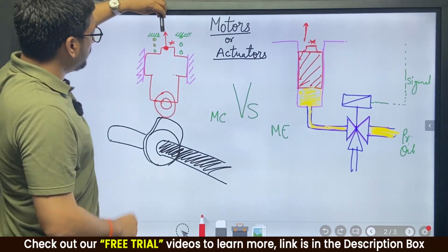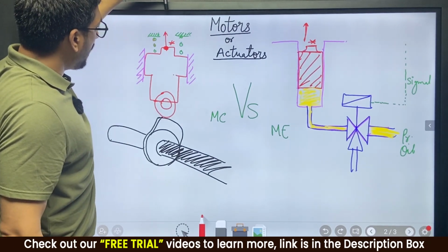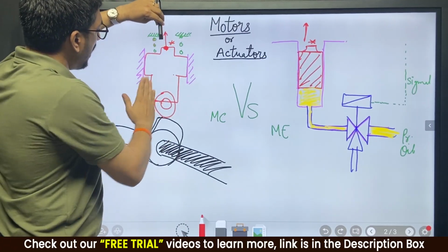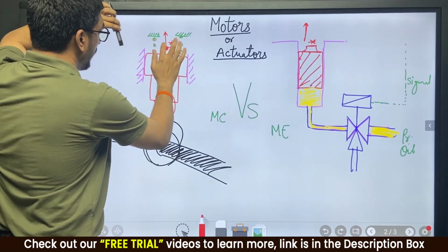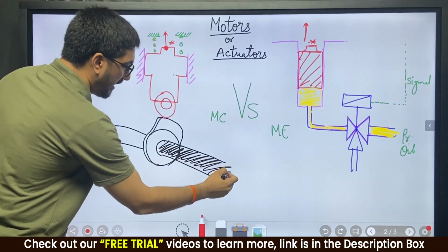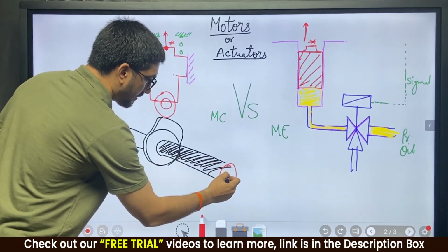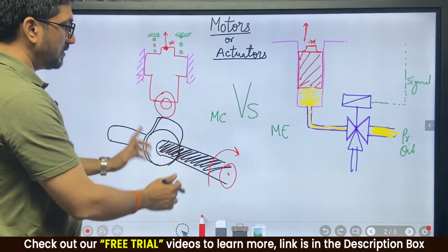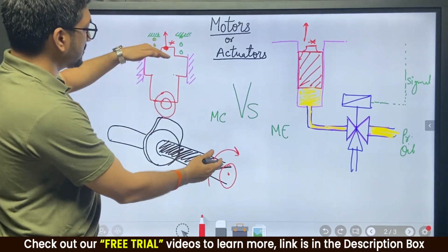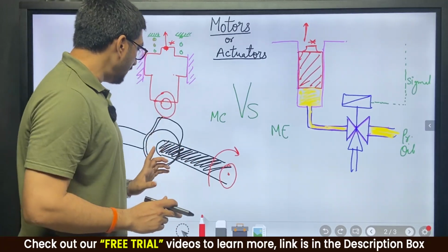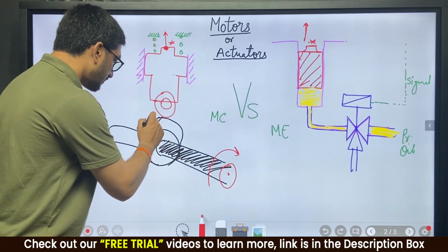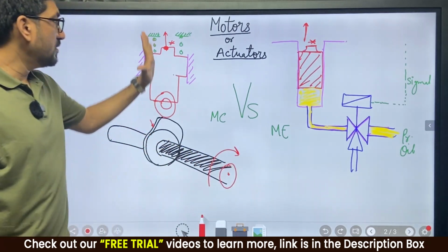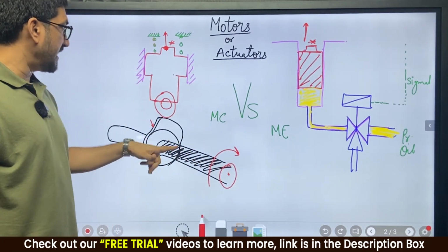You put anything above it, it will go up. There might be a spring which is pushing it down or something like that. So I'm getting a linear motion from this point, and this point is moved up and down by a camshaft which is rotating through this arrangement. I have got energy here. This is transmitted here. Again, timing also depends upon the position of this dwell as per the crankshaft position. So timing is decided. Power is getting the power.